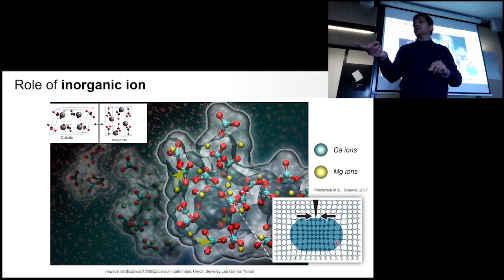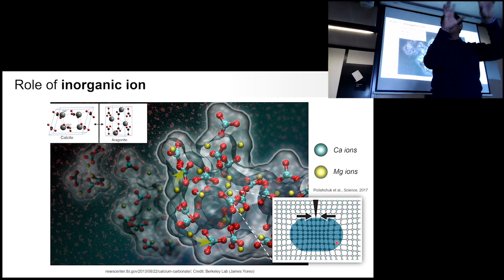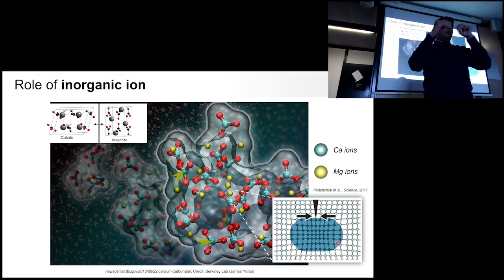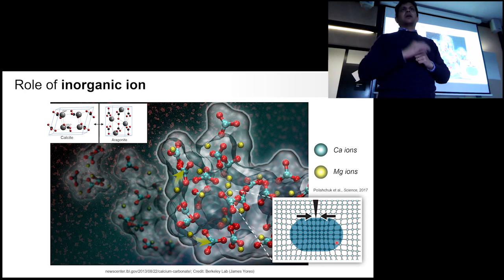Interestingly, that's the way Gorilla Glass is made. What glass? The glass in our mobile phone. This? Yeah, the fracture resistant glass. Well, all the phones are broken. Yeah, so they take the amorphous glass and bombard ions into it. The ions knock off the usual silicon dioxide structure in some places and induce strain, and that makes the glass impact resistant, fracture resistant.